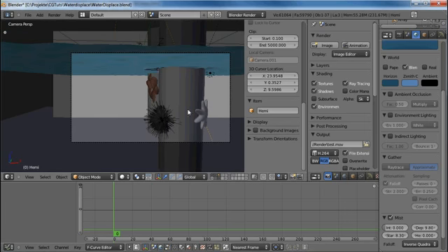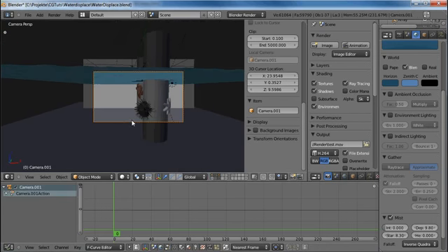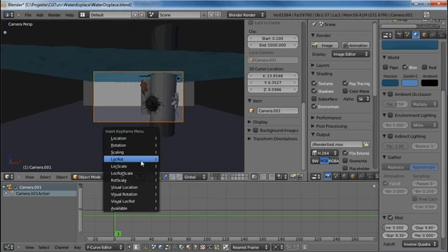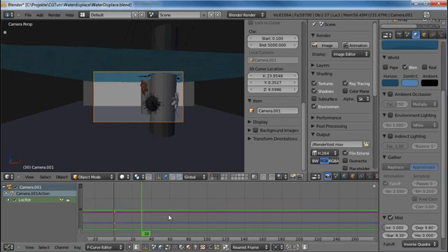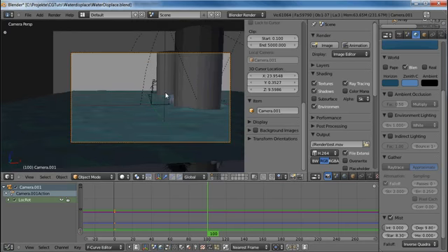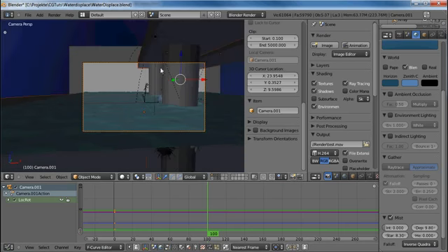So what I'd recommend you to do now is to make a camera animation. Click on the camera, frame 1, put it into place, wherever you want it. Press I to insert a location rotation keyframe. Then go to frame, let's say 100. I use 100 frames. That's however long you want to take to pass the surface, and move all the way through the surface. Maybe even move a little too high. Just make sure you don't clip that pole over there.